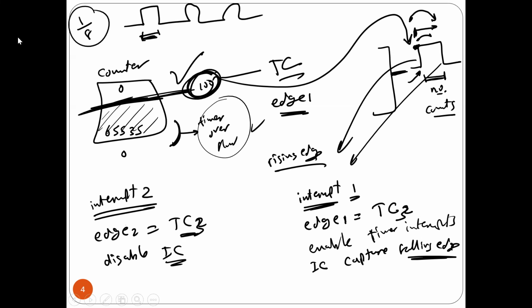So anyway, what I'm saying is that, guys, I want to measure the signal from here to here. Is that okay? So in the very beginning, I'm gonna enable input capture. Once I capture this one and I capture this one, now I'm gonna disable input capture, right? Unless I want to do another round of measurement. The reason I want to disable input capture here, guys, is that if you forget, once this one comes, you are going to change H1 and H2. You are going to change them before you finish the calculations.